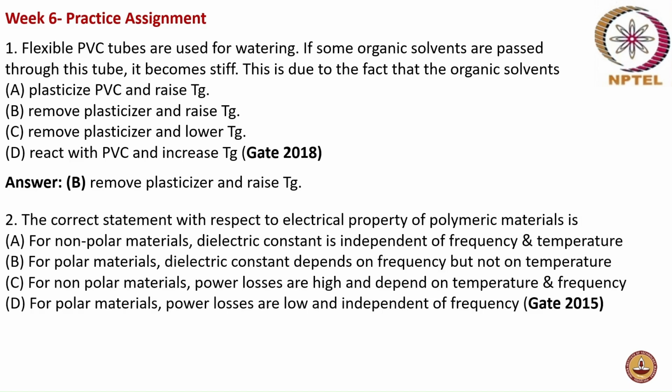Next. The correct statement with respect to electrical property of polymeric materials is: for non-polar materials, dielectric constant is independent of frequency and temperature; for polar materials, dielectric constant depends on frequency but not on temperature; for non-polar materials, power losses are high and depend on temperature and frequency; and for polar materials, power losses are low and independent of frequency.